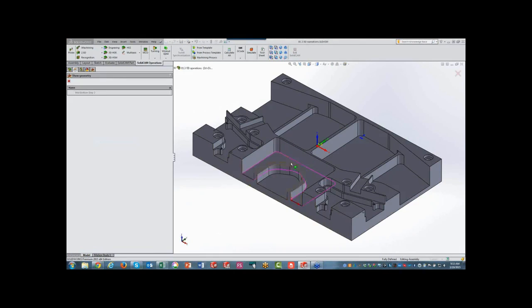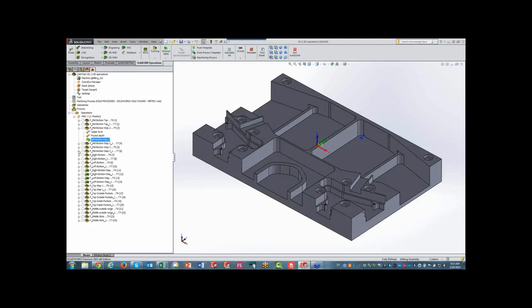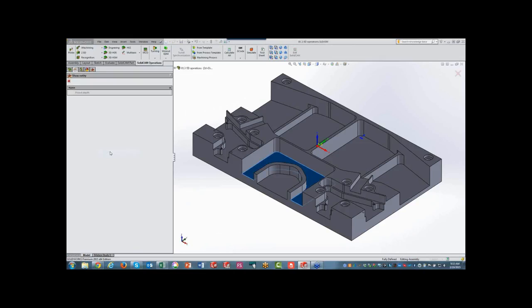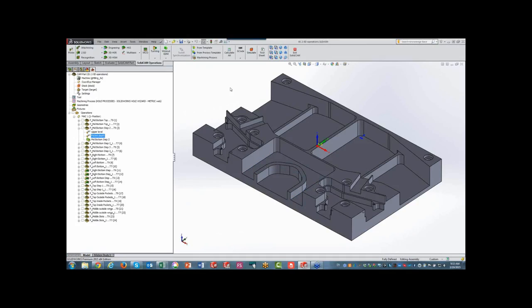So I have to have a geometry just for that area as shown over here. Obviously, my Z levels have to be different as well. You can see my Z level bottom is over there. And if I show you my operation, the actual tool path, you can see that my tool path is including this area over here only. Now, my next operation, again being the finish for that, we'll skip over that one.